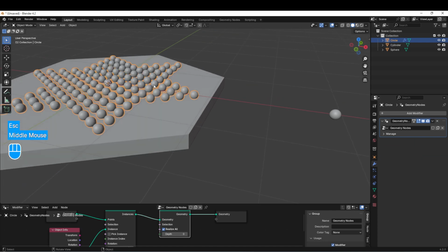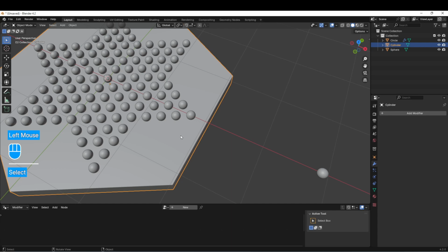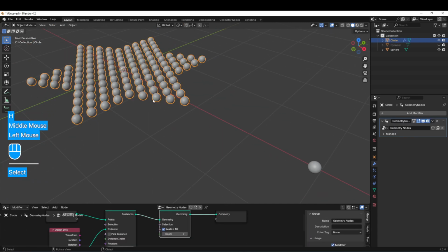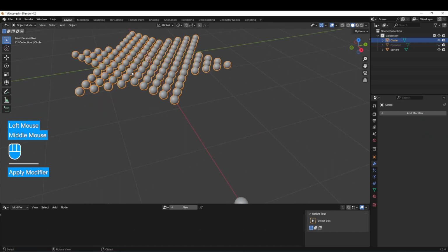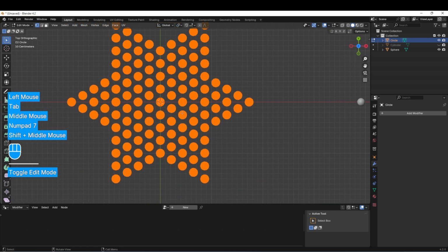Last, we're going to make our marbles to sit in that. So we don't need all of these. Typically you have enough marbles to fill the little triangles on the outside. Let's select the checkerboard, hit H to hide. And right now these are all pretend. So we need to make them real. To do that, we're going to apply the geometry node here in the properties panel. Now, if I go into edit mode, they're all real things that I can edit.